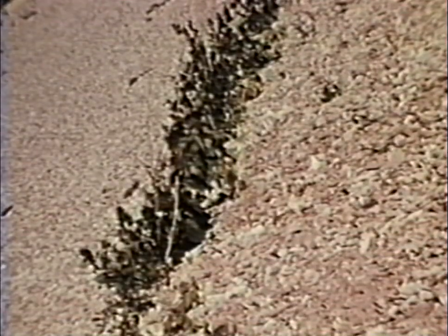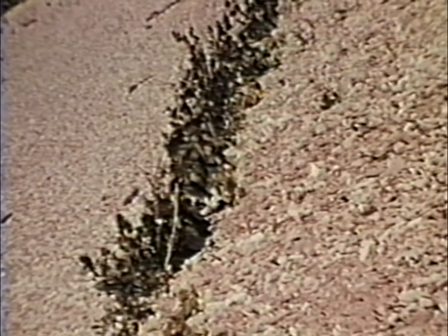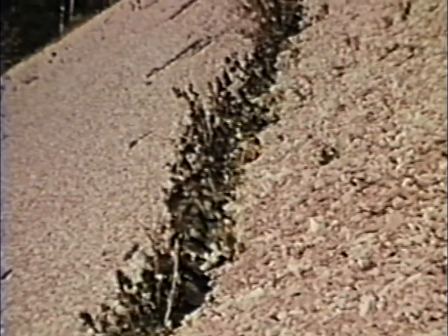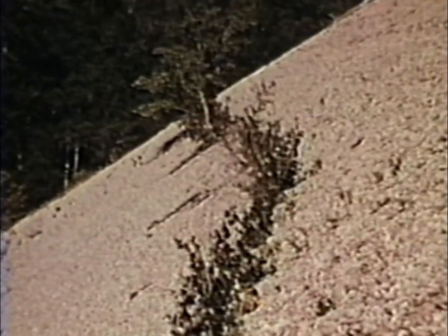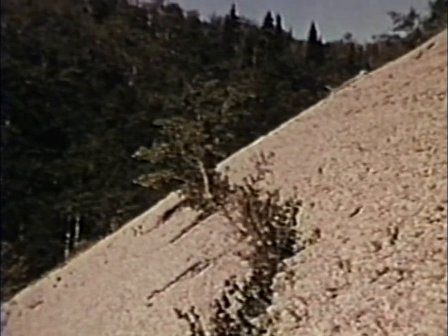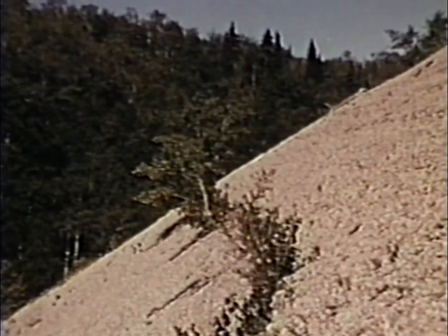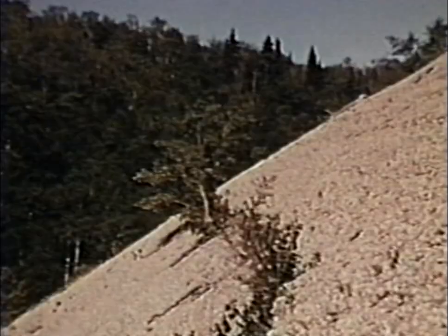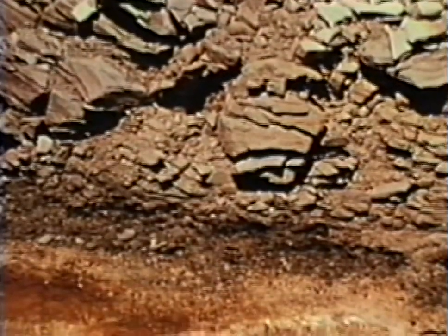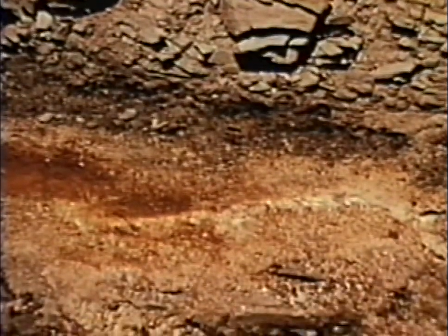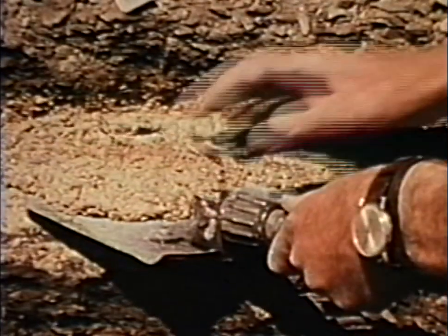On the slopes, parallel to the geologic layers, shrubs and small trees seeking moisture grow along a layer of moist yellow clay. Because of joints in the weathered shale, groundwater moves rapidly downward until it encounters the soft, impervious yellow clay. The groundwater is diverted along the clay layer to the valley slope.